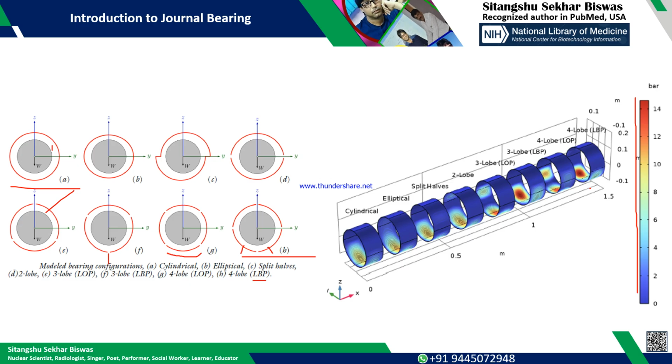While the liquid is coming out through the discharge, there is some hole. So due to discharge pressure itself, some portion of the liquid comes through the hole to the bearing area, and it is creating the lift force.